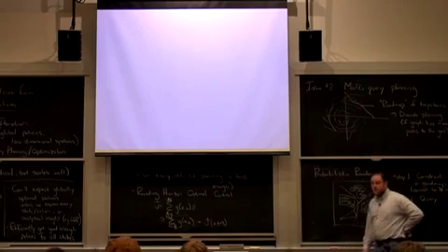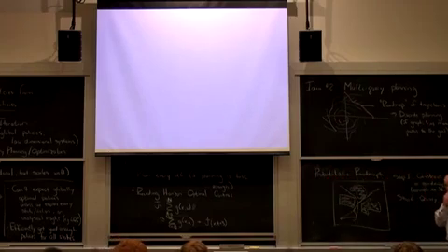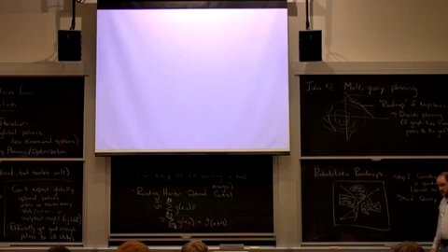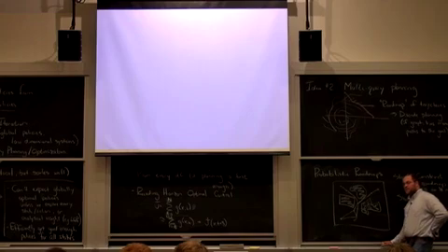So when you're doing the sampling here, RRTs do this very uniform sampling, and you say you can bias the sampling. Yes. But if you're doing this before you even do your first path, why don't you actually choose optimal sampling? Can you do some kind of Voronoi diagram with this and just say, I'm going to tessellate using the best I can find given that I have a model of the world, and then get done with sampling? You're still in continuous time, so why is the sampling still part of this?